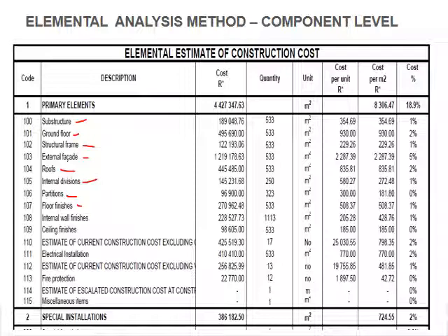Okay, so this is usually how you build up your estimate. I didn't include the special installations and so forth, but your primary items are calculated here, and then you've got your quantities here, and you have your rate that you've calculated from your previous buildings, and then you multiply that to get to your total estimate for the project.